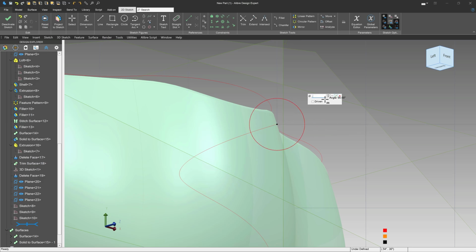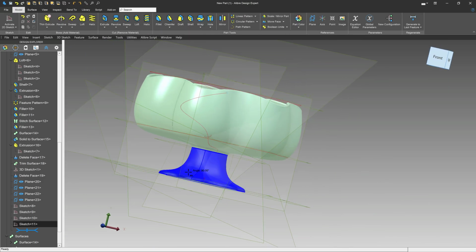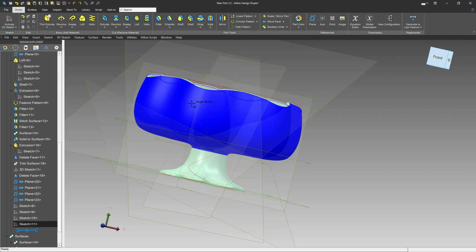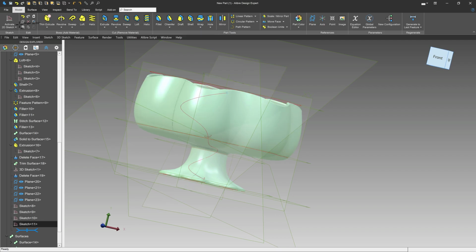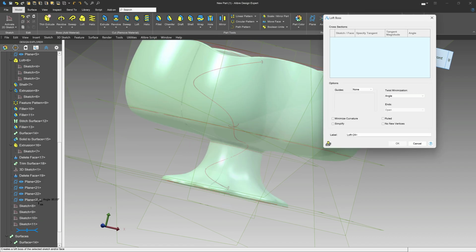And we want it to be small again, right? 0.1. So we're going to have a loft, a centerline loft, that runs through here for features of various sizes, or a feature that changes size as it goes. So I'm going to choose loft over here, and I can choose each of my sketches that I've made.